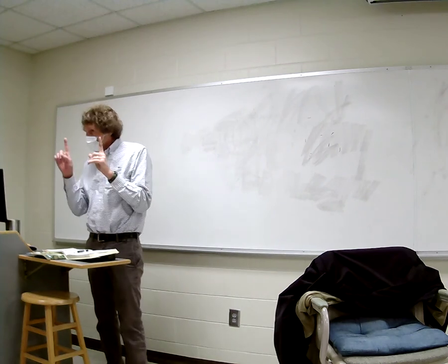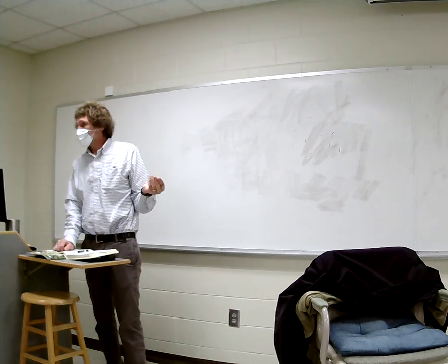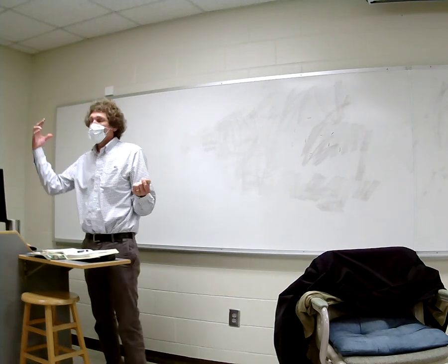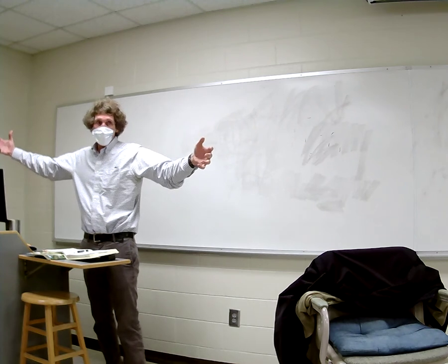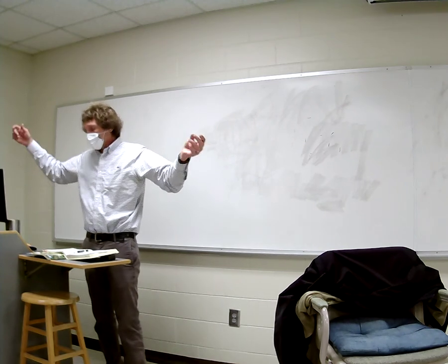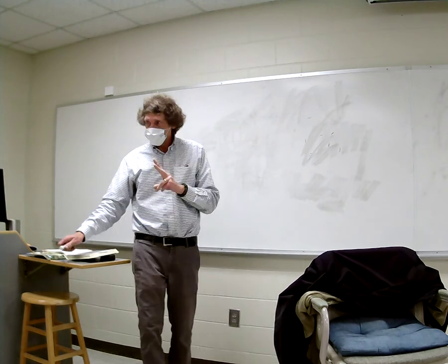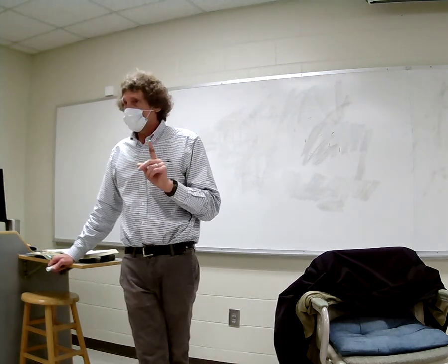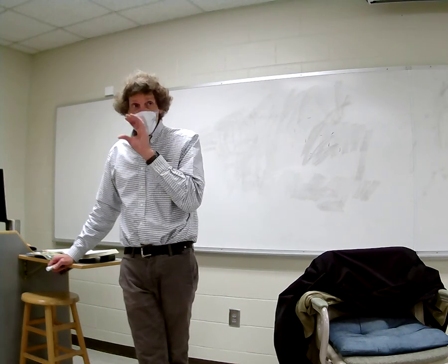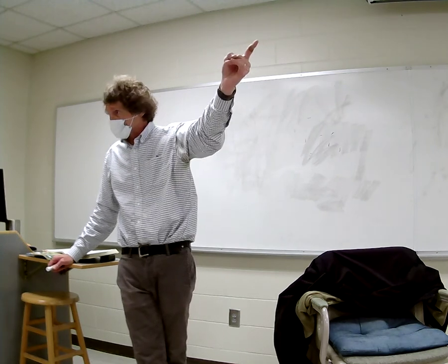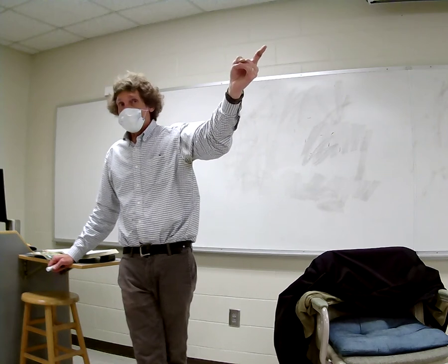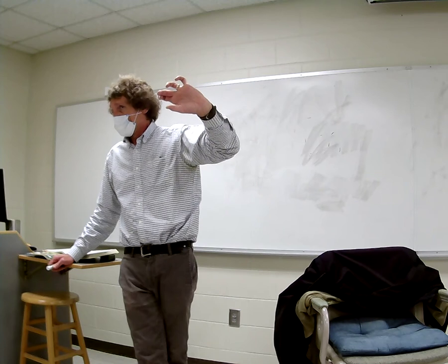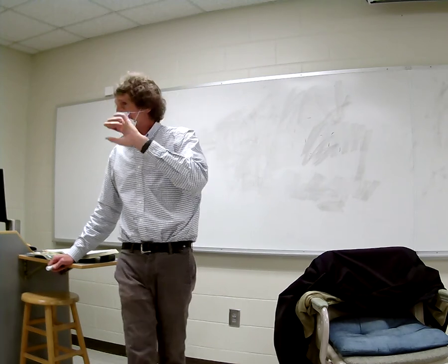You also learned about Friis, right? In a nutshell, what does Friis' equation tell you? Anybody? Power received. Yeah, if you have one transmitter and one receiver, you figure the amount of power received, right? With the power received, there are two important things. You take lambda squared over 4 pi times the gain of the antenna in the direction the signal's coming from, and then you multiply it by the power density at the antenna. That will give you the amount of power received, but that's not how much power you can get out.